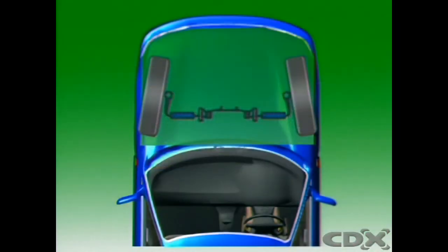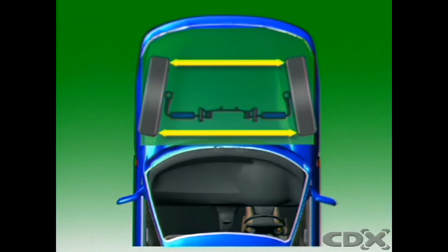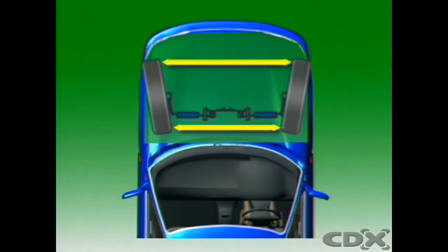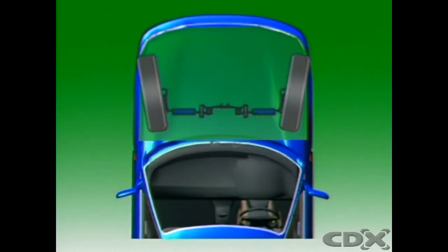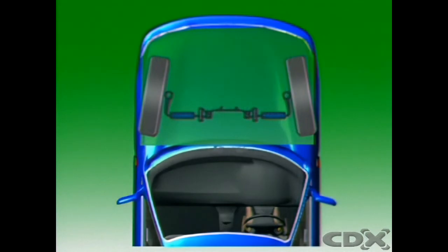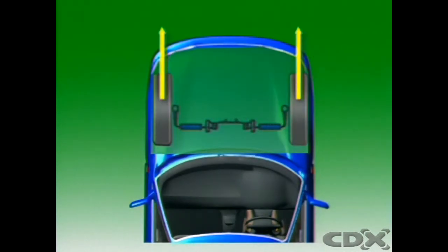When the front of the wheels, as seen from above, are closer together than the rear of the wheels, it is called toe-in. The opposite arrangement is called toe-out. The static toe setting is designed to compensate for slight wear in steering connections, which may cause the wheels to splay outwards or inwards. This means the wheels will be parallel when the vehicle is in motion, which avoids road scrub.